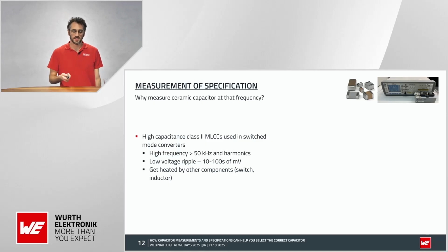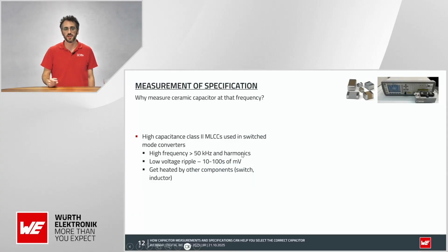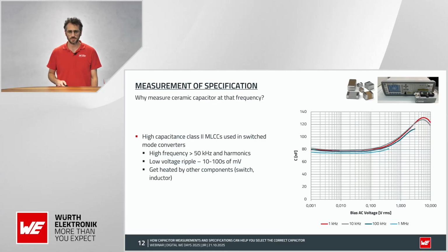Again, this maybe is not related to your application. In your application, maybe you have a switch mode power supply. So maybe you have a switching at 50 kilohertz, maybe a ripple voltage of some, or maybe hundreds of millivolt. So it's totally different. Also, the temperature is different from room temperature because probably the capacitor is getting warm from other components.